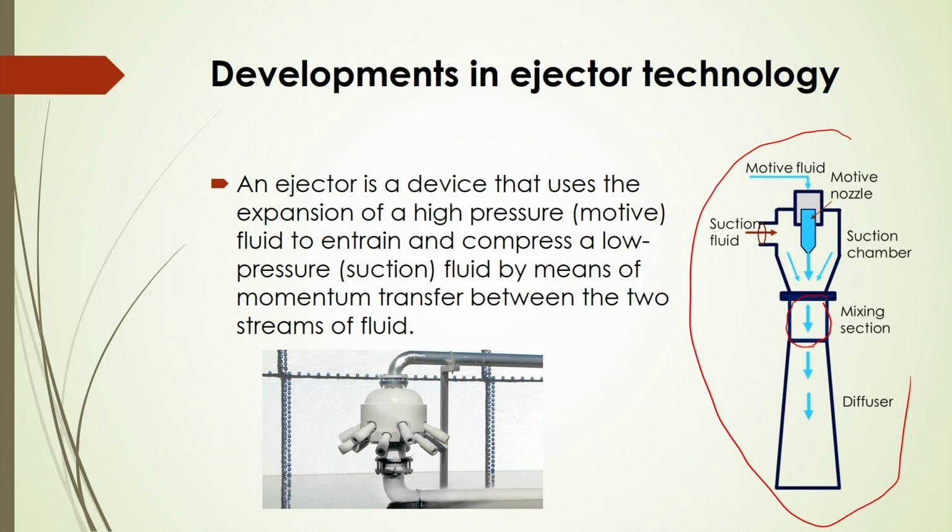In this case there will be high pressure creation, and in the diverging section there will be low pressure creation. Whenever the liquid sucks gas, it comes out through the liquid and is entrained in the contactor later on. In this contactor there is a pool of liquid, where this liquid jet plunges and the sucked gas is entrapped in the liquid. So, this can be used in several chemical engineering operations.